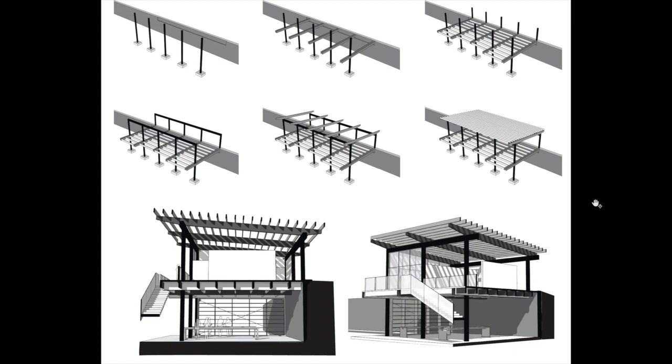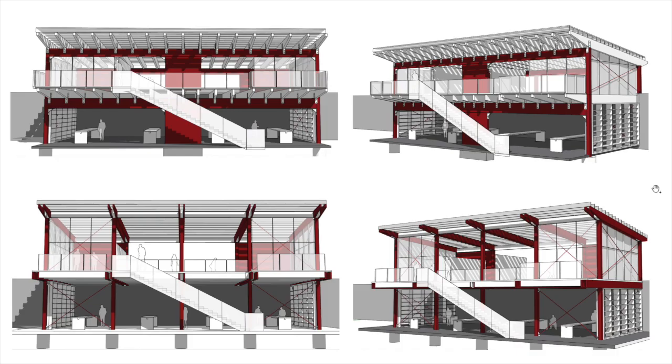What if we did cantilevers then with option 2B? In this, again, we have the same number of columns. In this case, the girder, we almost have to sandwich on both sides of the column. We can't have a cantilever that comes out this way and somehow magically goes through the column. We have to put one on both sides. In doing that, then, we can still run the purlins in between. We can still have a stairway that's run out front, stack it up above. The more detail you start to add to this, the more you start to understand the depth and the construction, you add a sense of realism to it, which really helps you to evaluate the quality of the design that you have.